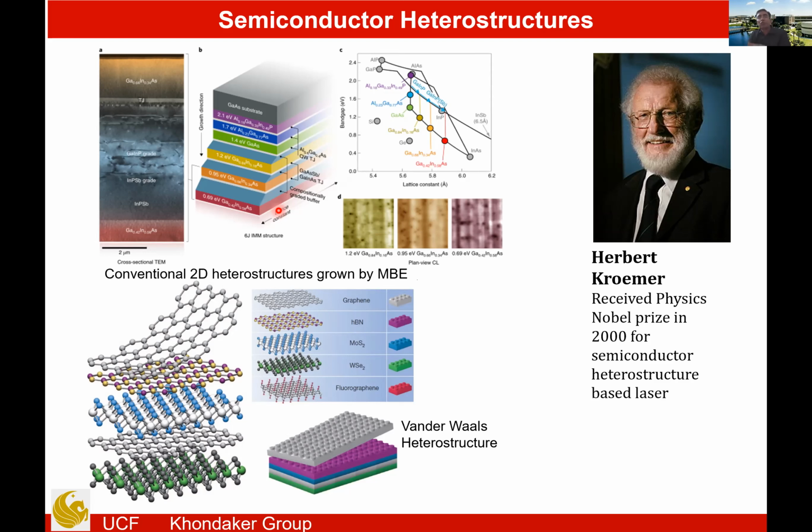But the issue is that when you choose those materials, you need to keep in mind that the lattice mismatch between two layers that will be grown on top of each other cannot exceed, as far as I know, more than 7%. Otherwise it will not grow. It will nucleate and have something else. You can't grow a crystal lattice that has a significant lattice mismatch. And of course, this fabrication technology is very expensive. You need molecular beam epitaxy because you are growing semiconductors. You have to be in an ultra high vacuum environment, okay? Very sensitive. And it's very expensive too.